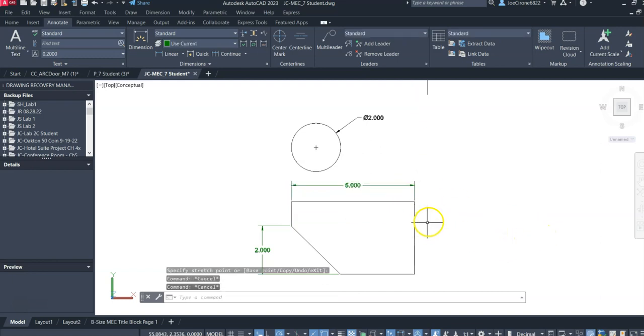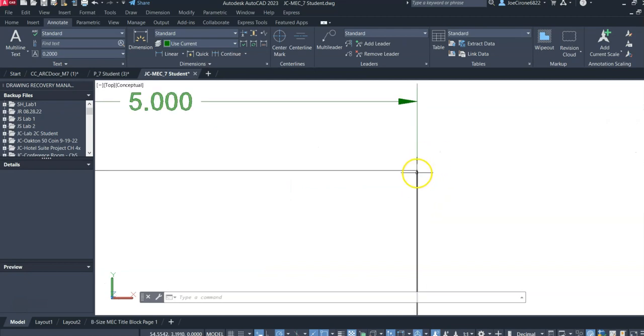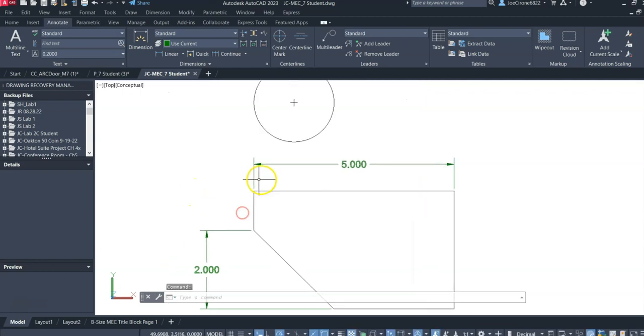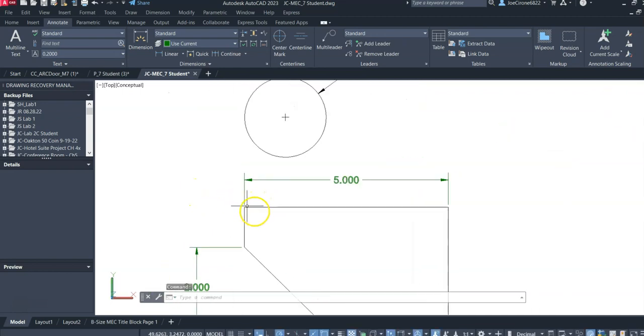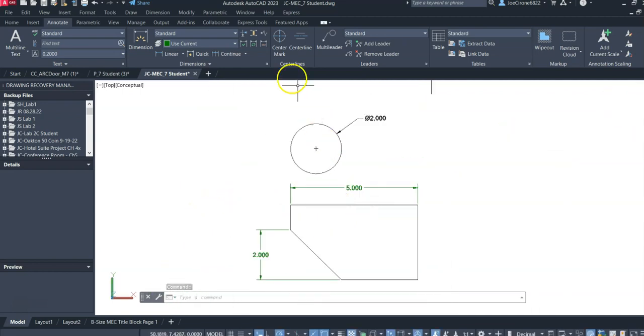What about 3/8 of an inch to 5/8 of an inch off of the part, depending on how close it is. There is no specific rule, and if you go through an engineering graphics course, they'll tell you to have some spacing. But the ideal is that you'll use an endpoint. There should be a small gap here, which will automatically be created when you create that dimension. And then we just place that dimension.